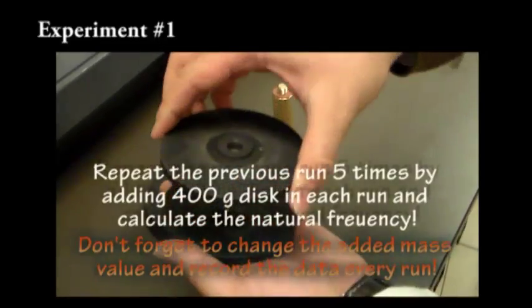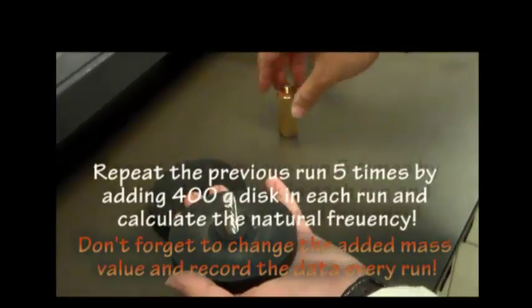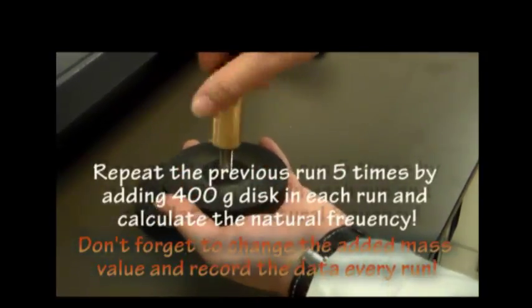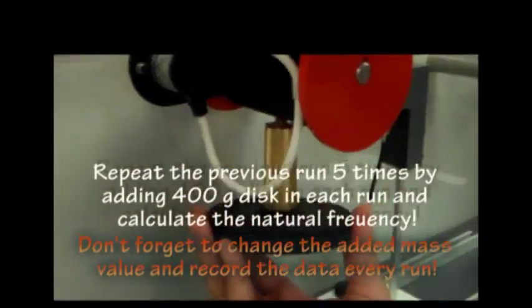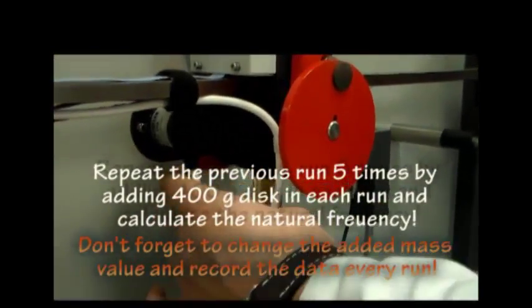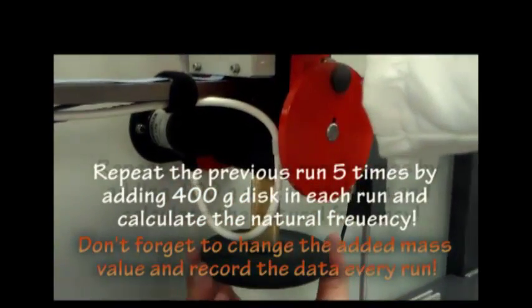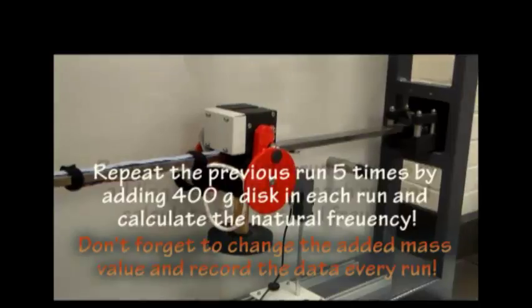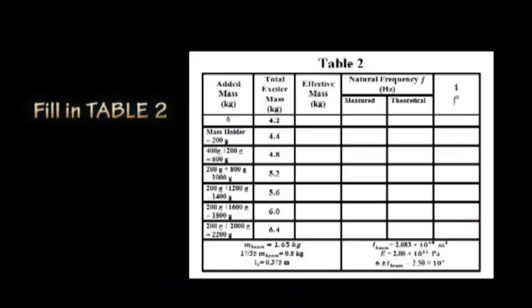The third to seventh runs. In each of the following 5 runs, add one mass of 400 grams and repeat measuring the natural frequency as you did in the previous runs. Remember to update the added mass field in VDAS. Please note that you might need to readjust the set 0 control before finding the natural frequency. Fill Table 2 with the required measured and theoretical values after finishing each run.